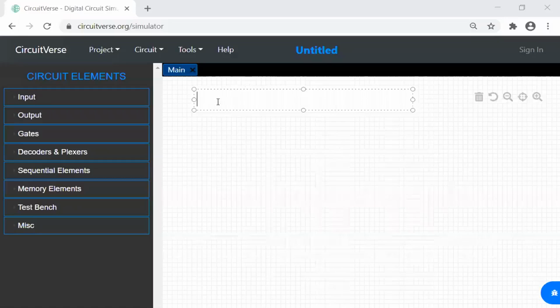Now the truth table for D flip-flop has the input D and the output Q. If D is the input, the output will be the same. If D is equal to 1, the output will be equal to 1. Now what about the excitation table for D flip-flop?